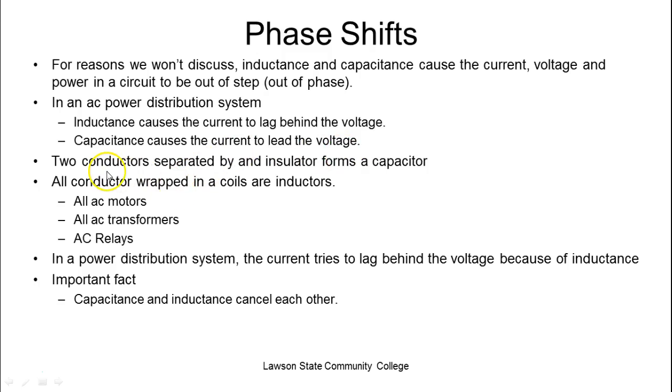Now, this phase shift is required by single phase motors. We can't make a motor rotate unless we have a field that is moving in reference to another field. So AC motors are going to have a winding they call a start winding, and they're either going to use an inductor or a capacitor to cause a phase shift in the start winding to cause the single phase motor to spin.